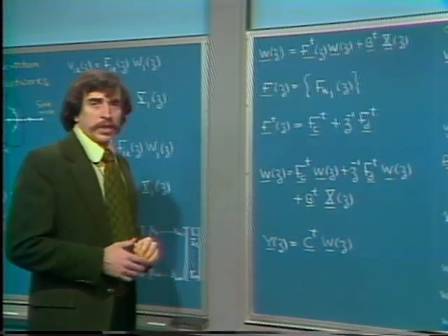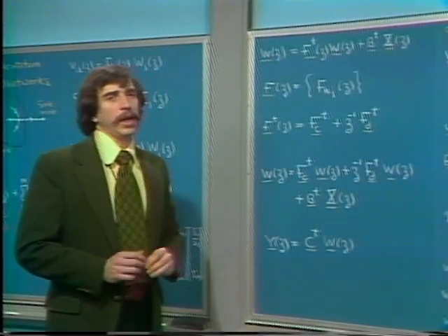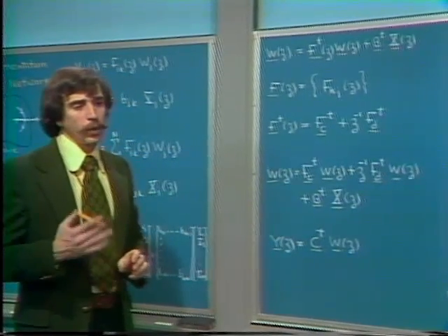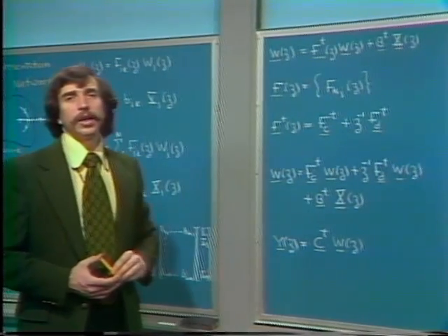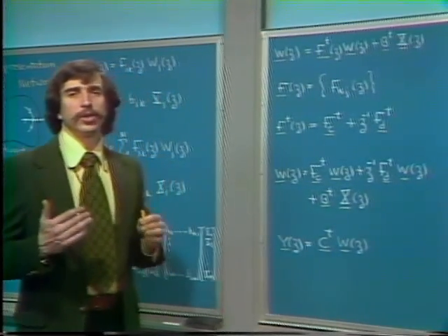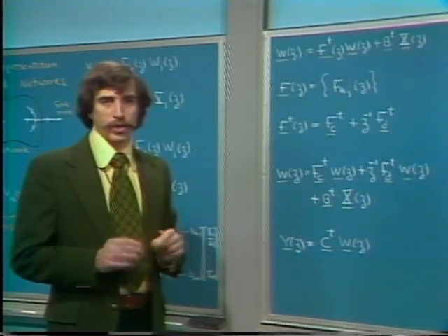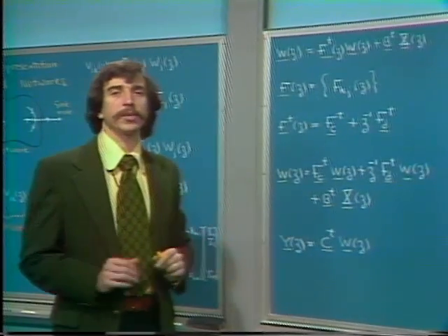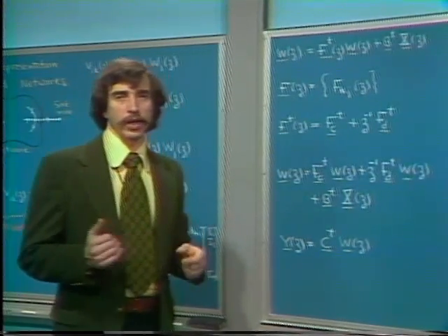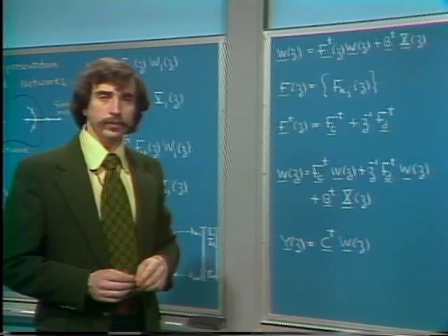It's typical, and notationally what we'll also stick with, in representing a digital network with flow graph notation to restrict ourselves always to branches that are either simply coefficient branches, in other words, they correspond to multiplication by a scalar, or they're simply delay branches, in other words, they have a transmittance which is z to the minus 1.